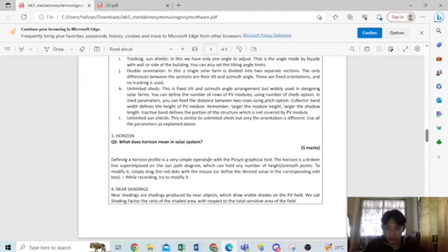The horizon is an important factor to consider in designing a solar system, particularly for solar panels that are mounted on the roof or ground mount. The horizon can obstruct sunlight and prevent solar panels from receiving direct sun. This can result in reduced energy production and low efficiency of the solar system.